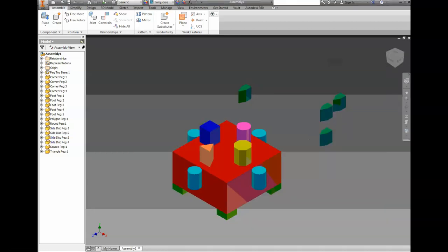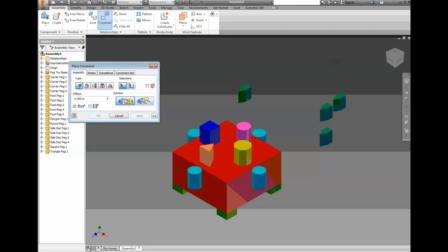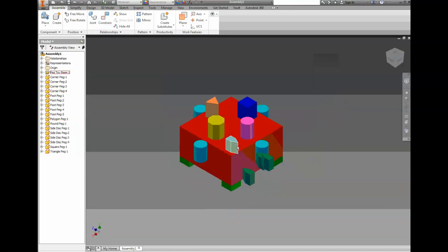We can see a picture of it. So we're looking at our home view. What we're going to do is we're going to mate. Obviously, we're going to mate to the top of this or to the top of this. So it's locked on, okay. And I hit apply, and I'm going to go over. If I hit cancel, I can look. It moves around. Well, it's stuck on that face.